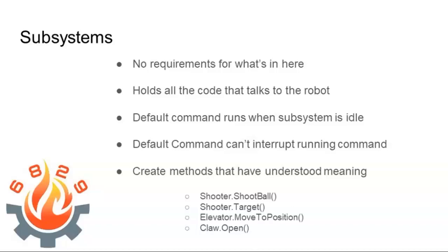You could put it down while I'm driving, right? And so what happened was, they're trying to drive back, and our controls for the drivetrain to drive the robot were a default command. So he's trying to back up, but the command to raise, back up, and lower, which took like a second and a half, was still running. So he could not back up.